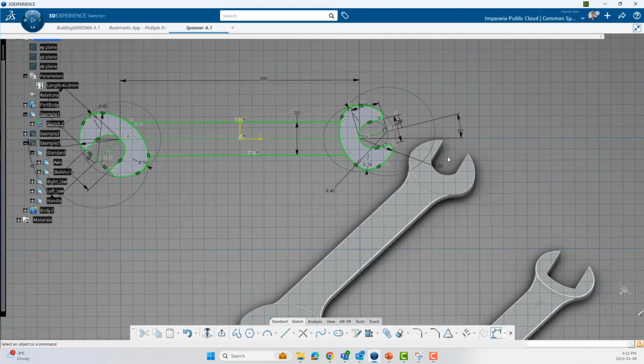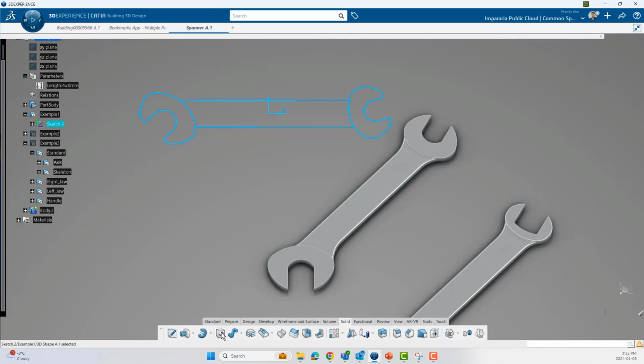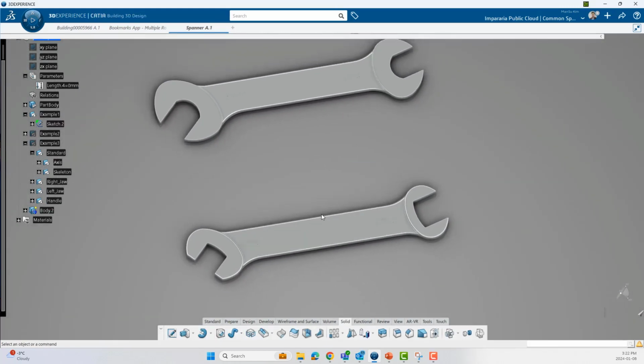So for modification, you need to consider creating it until here. But when you create until here, this will open and clash with the opening ways. Therefore, we divide the design intent into a work breakdown structure and build separately, and consider when the connection process should be done. In this case, the connection process is done after creating this body and this body, not from the sketch. Those are very crucial for your design modification.